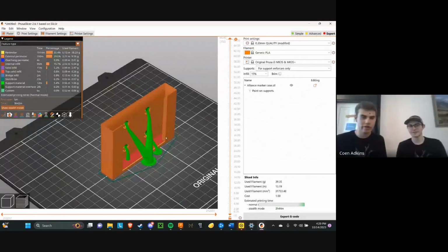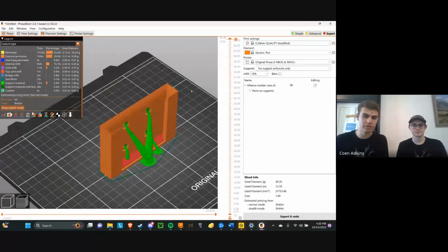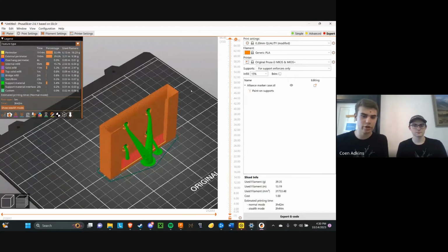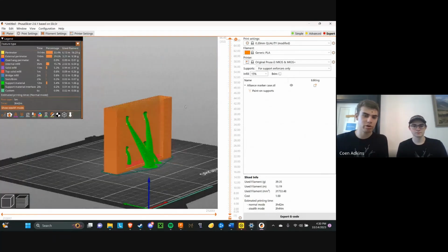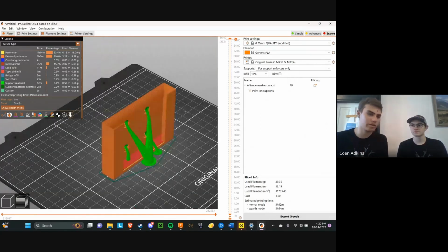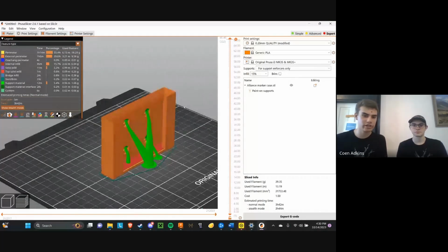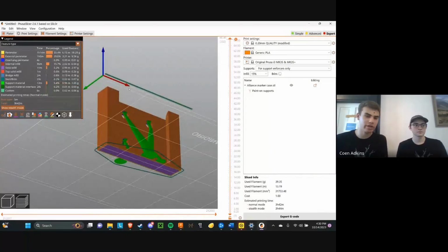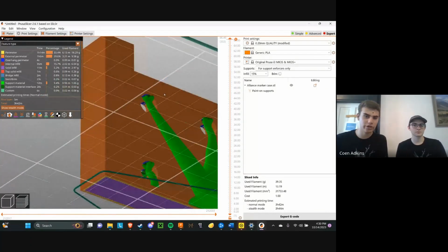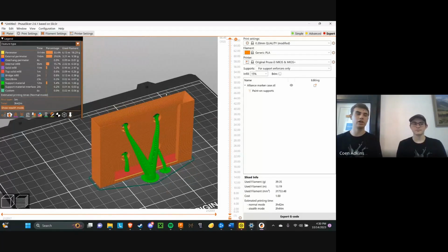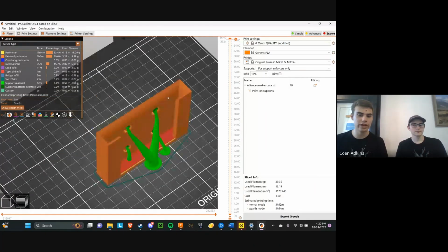Yeah. I've messed around with a couple of other slicer softwares, but I mostly use Prusa Slicer. It does a really good job of letting you know if there's a problem, like if the part's not going to stick to the bed because of little surface area. Or if there are big overhangs that can't be done, it'll show the blue here, and you can obviously see there's a bunch of blue, and it's like, okay, I should probably put some support material there. So it'll give you recommendations on how to make your parts better.